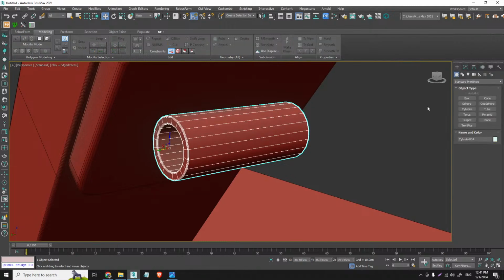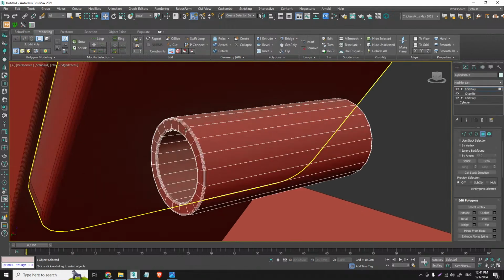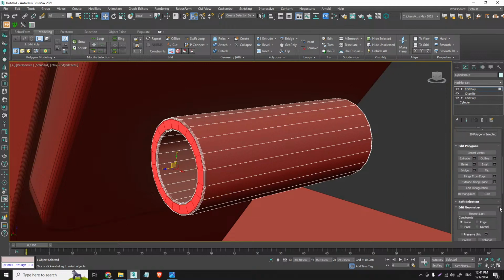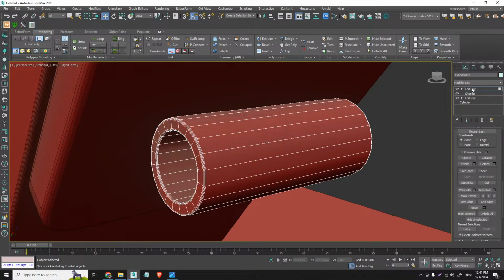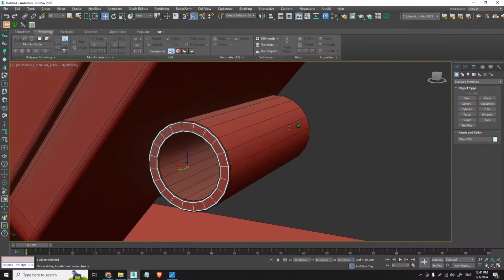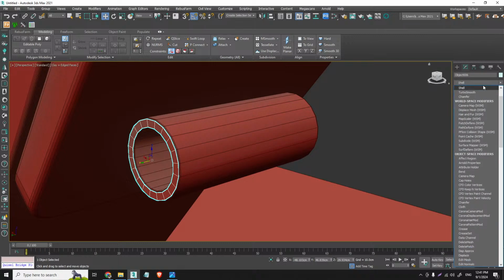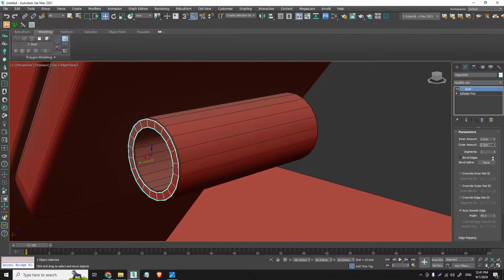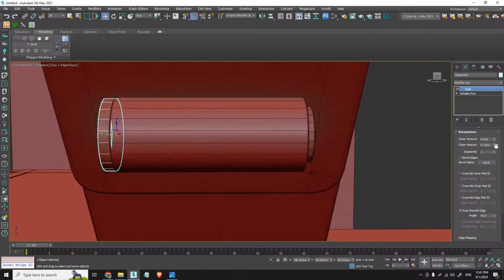And now let's also create the other one, which, like we said, we need to select this part. I just clicked on this and pressed Shift to loop the selection. And I will detach this as a clone once again. And I will scale this about here, maybe a bit more here.